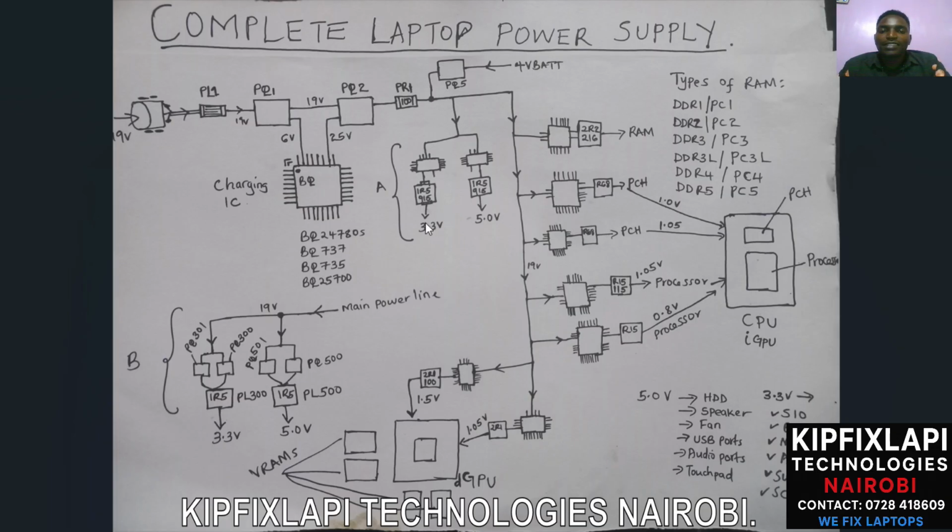I can give you some examples where this 3.3 voltage can cause problems. Down here, I wrote a few components within the motherboard which need this 3.3. So this 3.3 generated at this circuit is sent to, but not limited to, these components. These are just a few components which need that 3.3. One, we have SIO.